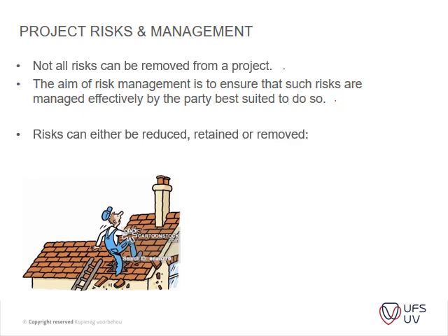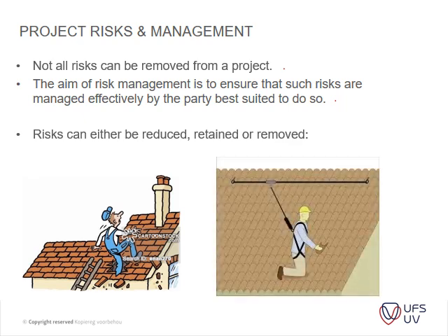Especially on a steep roof, an accident can happen very quickly, and simply using a harness, you can improve the safety of the personnel on site considerably. Obviously, roof installer specialists will be more equipped to have safety harnesses and PPE available.